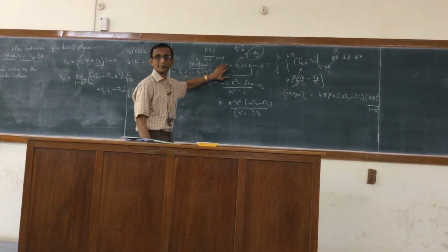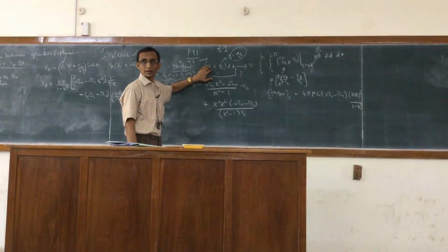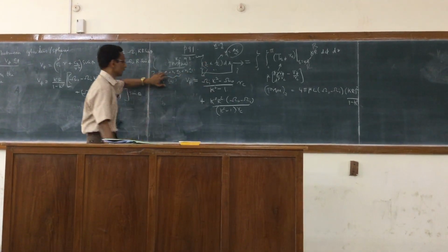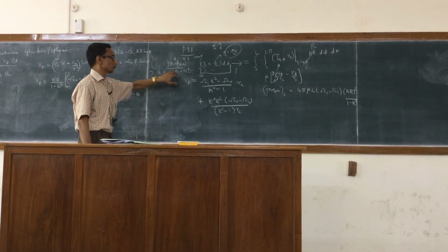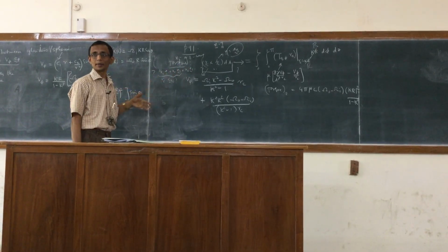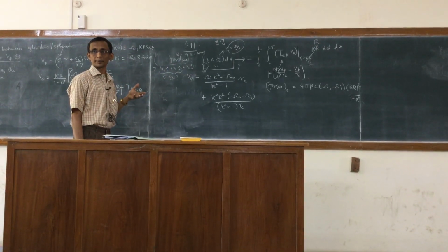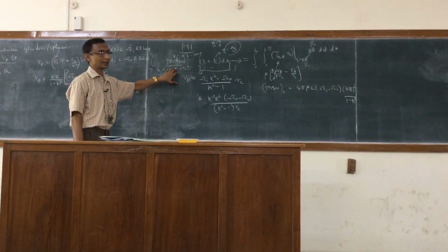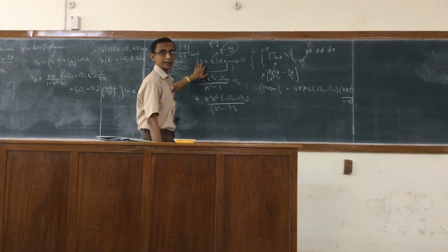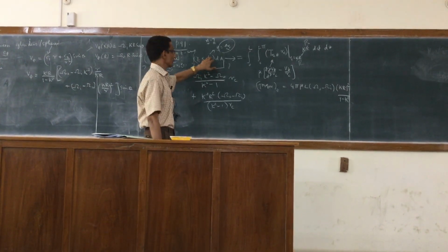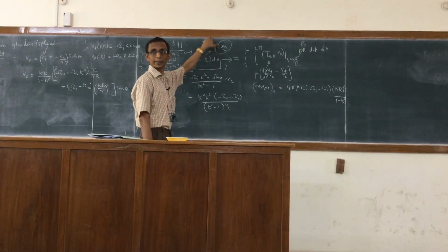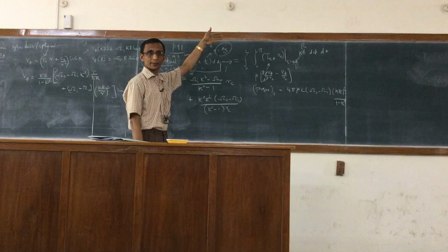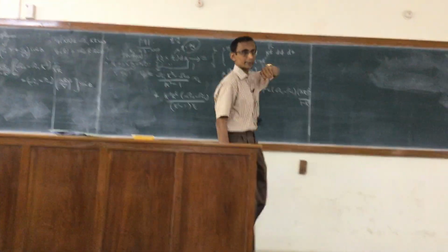You have to express this in terms of cylindrical coordinates. That's very easy to do because we know how e1, e2 and e3 are dependent on the cylindrical coordinates. But e3 is just ez, it stays the same, so you can easily get that. Right? So put all that in. Take the cross product. Now T would be n dot T, as expressed in cylindrical coordinates. Right? That is the components T r r, T r phi, and so on.